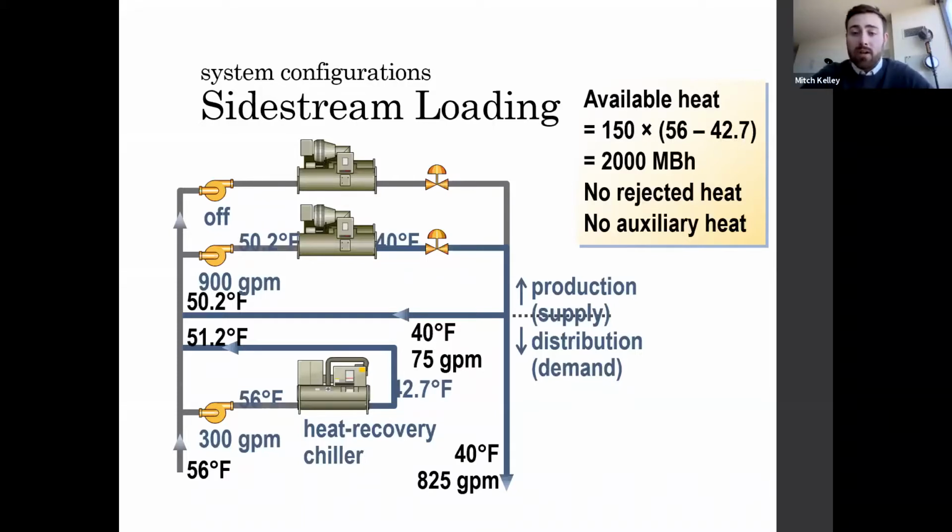It can produce whatever water temperature is necessary to exactly meet the required heating load. This allows the cooling to be produced at a higher chilled water temperature, resulting in more efficient operation for this particular chiller. Because the heat recovery chiller is controlled to only provide the amount of heat required, there may be no need for this chiller to be connected to a cooling tower. This allows a single condenser chiller to be used in this position without the need for a separate heat exchanger.